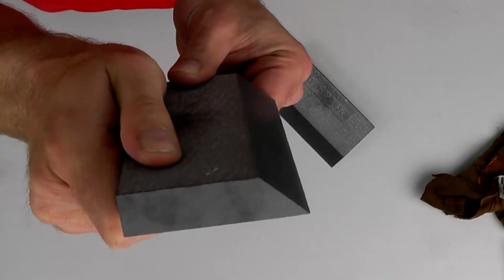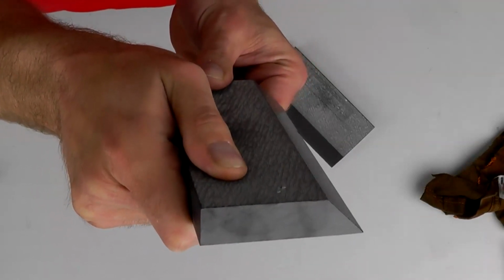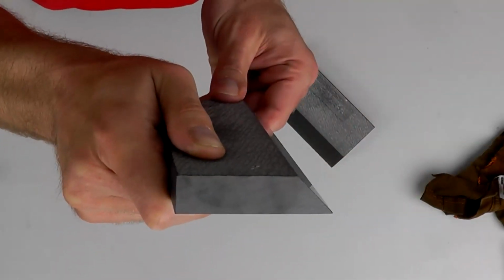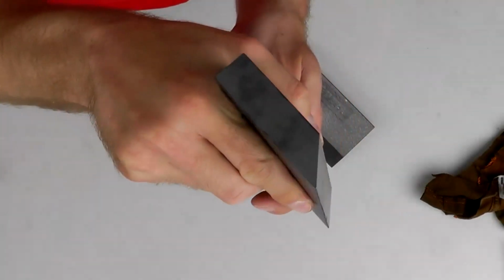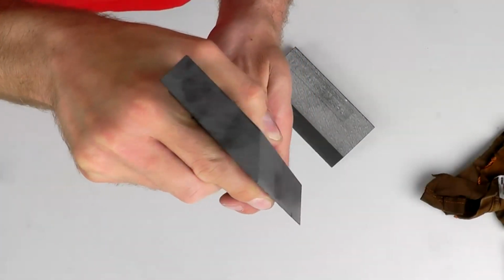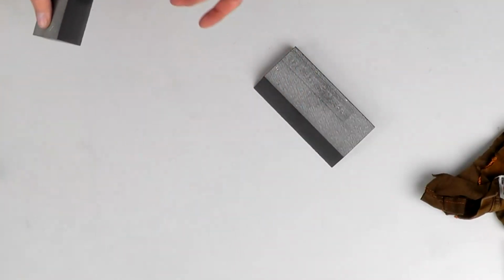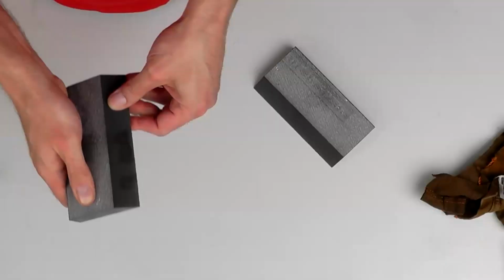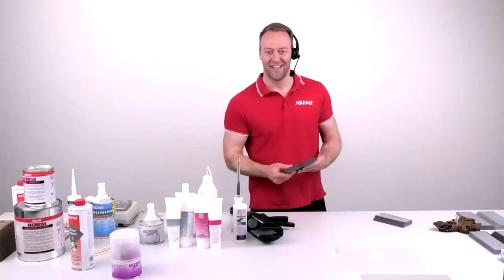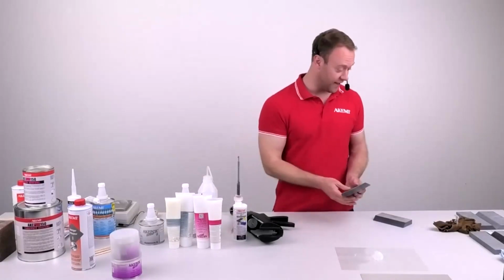This is a fully polished surface, and this is just from the cut. Nobody was sanding there afterwards or polishing or anything. So this is the cut, and this is much too smooth for proper bonding. You can see here it's a polished surface. Oh, here you can see it better. Nice. So no way of a good adhesion here later on. So always make it rough, and then you can see also here my greasy lunch finger I placed there. So this is also not a good preparation for bonding. So it must be rough, it must be clean.